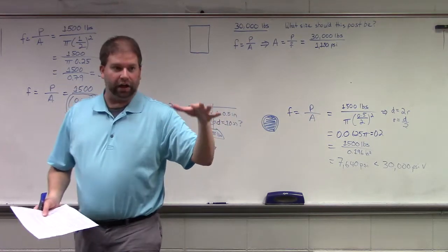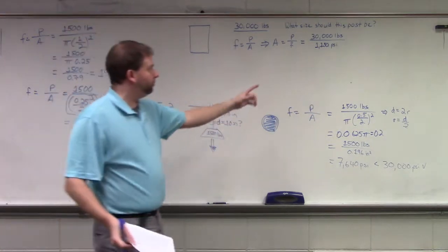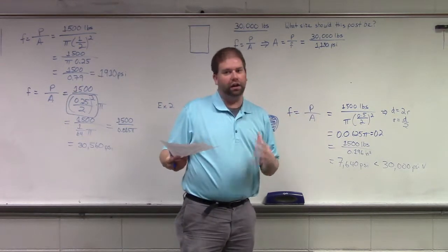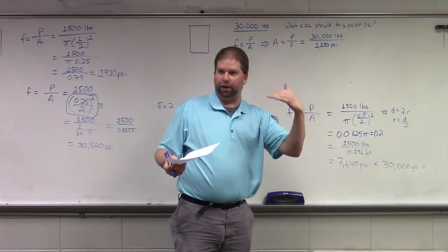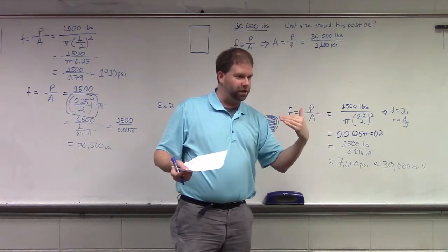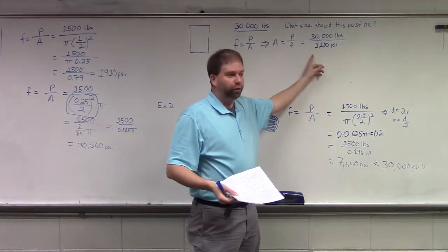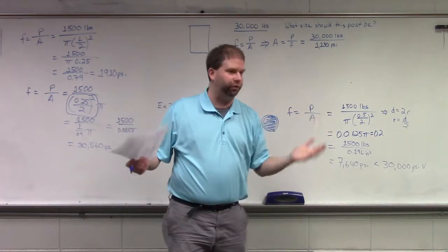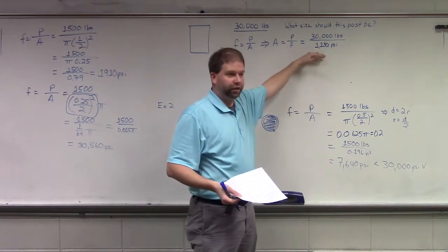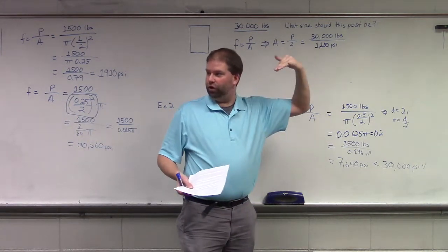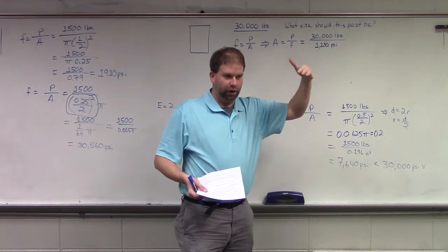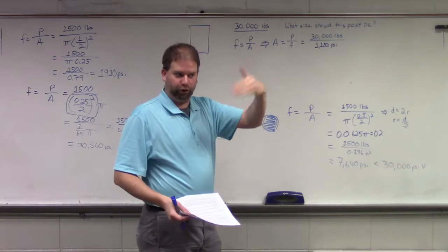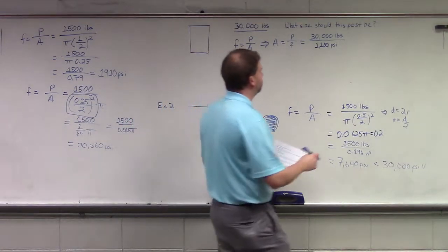Now, Terry brings up a good point. Does that mean that all the structural lumber, as soon as you put 1151 PSI on it, is going to completely disintegrate? Not necessarily. That's just the minimum allowable. We design to be conservative. What you'll probably actually see is ranges from 1500 to 3000 PSI, and so we reduce that number to make sure that we have safe construction. Once we get through analyzing this, we'll move on to the stress strain curve and talk about those types of things and why we do that.